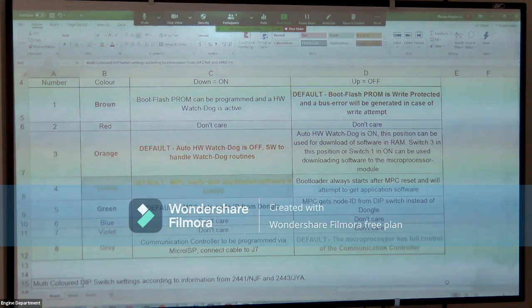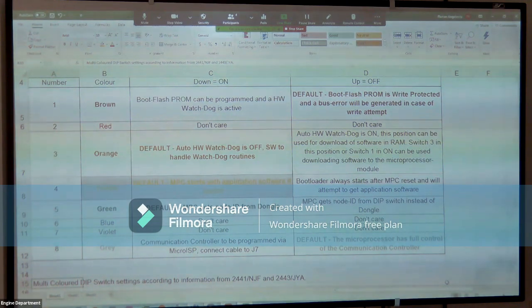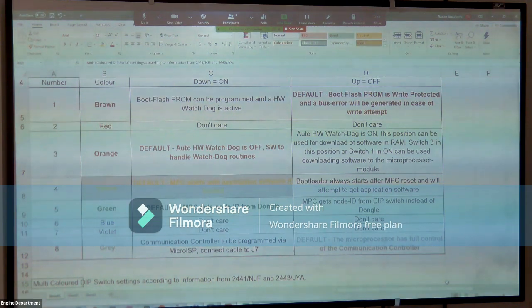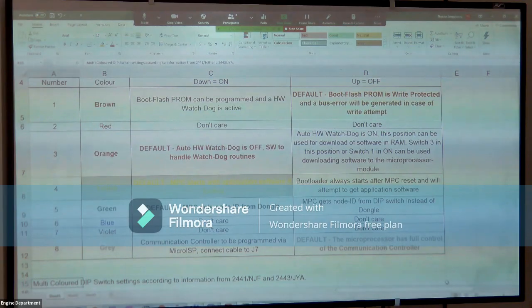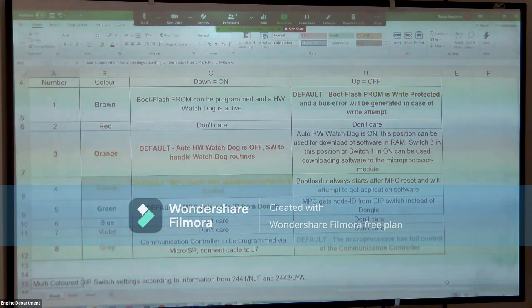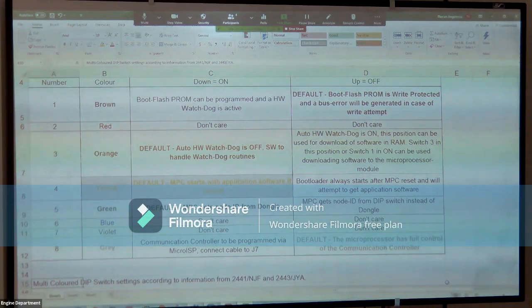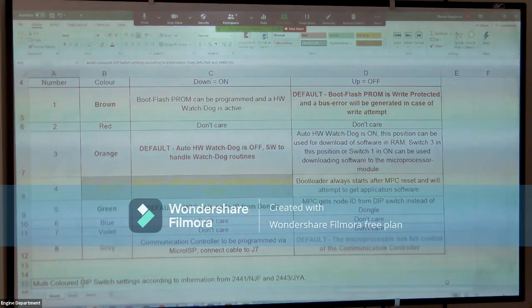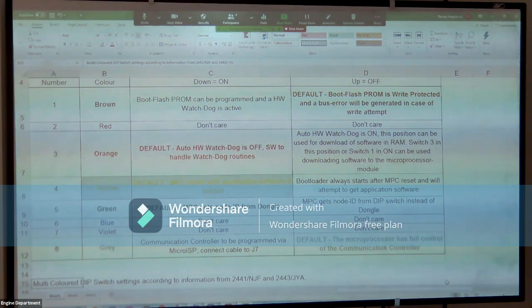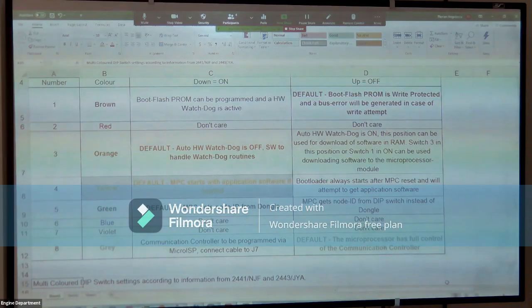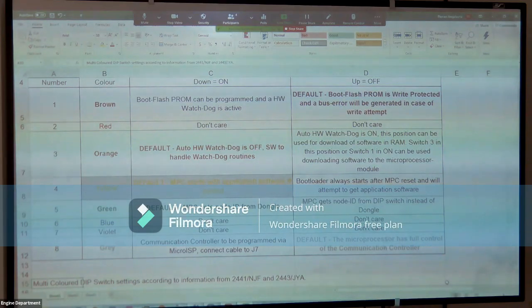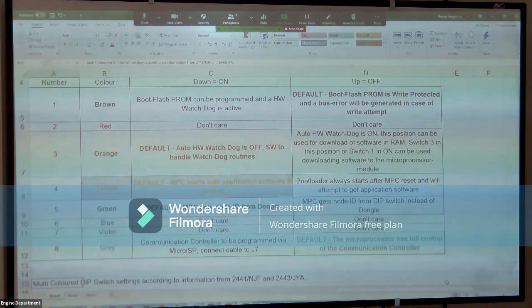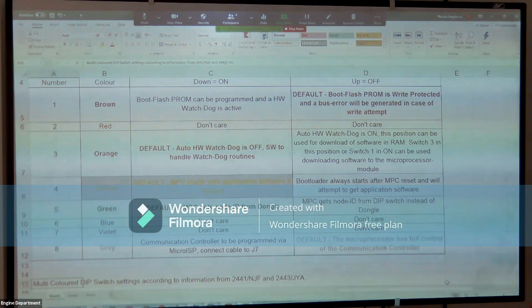It's important to know that the purpose of the ID key is to give the appropriate information about the software which is required to be installed on each MPC. In case the ID key is corrupted and the MPC is reset, it is required to configure a new ID key according to the section S1 from the operating manual, if this is available, or from the procedure which I showed you earlier.